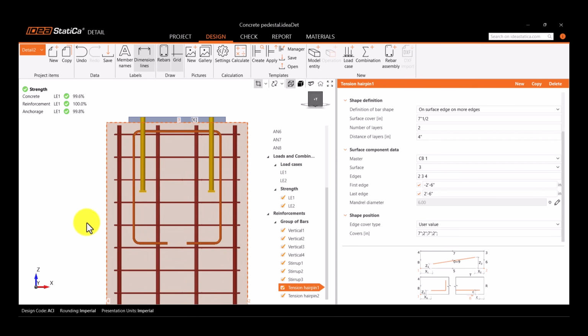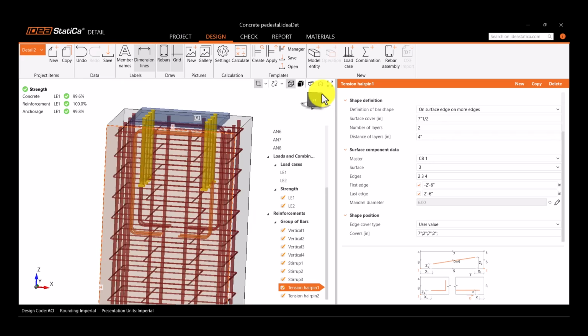All right. So in this case, I'm not showing all my iterations, but in the presentation, you can see the different iterations I did. I tried out using tension hairpin without this hook, and I was testing different lengths, so you can see how the anchorage is changed and how you can relate this to your development length calculations. But anyway, this is the one that worked for me with this 90 degrees hook. And then I have 30 inches length in total for this hairpin, right?